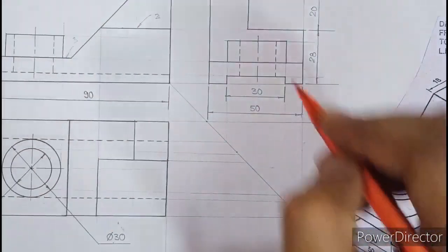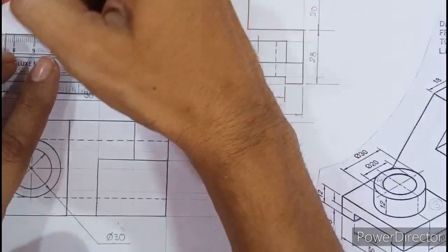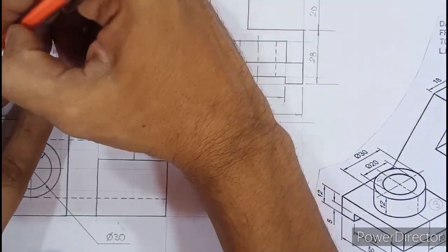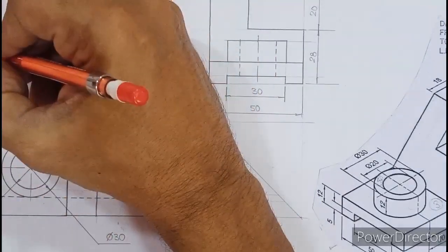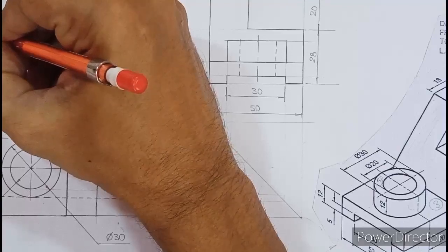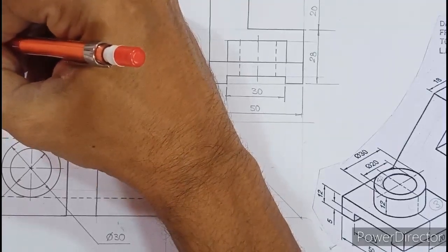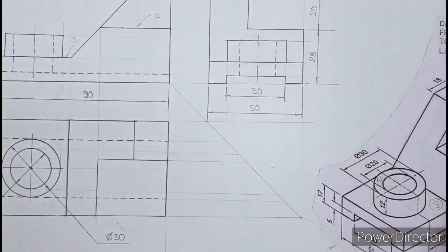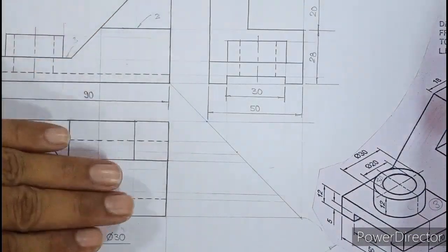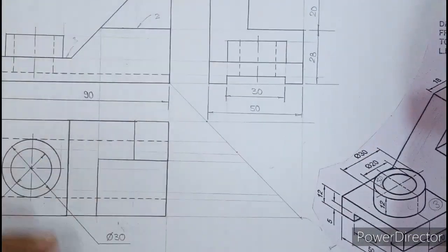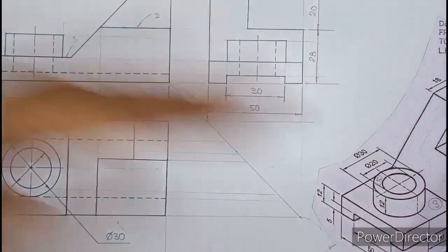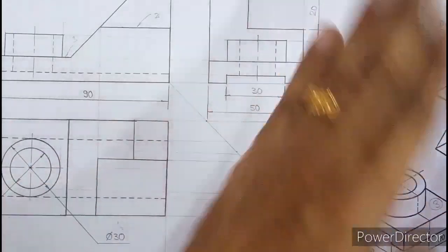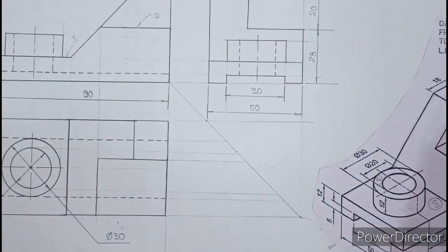Okay, height of the cylinder is 12, so 12 can be shown here. So we can show 12 like this. So that is how dimensions are shown. Always show the dimension above the line. See, this is called above. Look at 90, 18, 30. Look at this 28, it is above. Okay, so above means when you turn the line, the dimension should be above. So these are the standard ways to show dimensions.